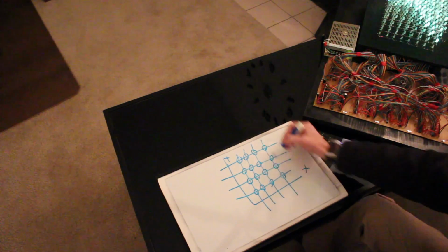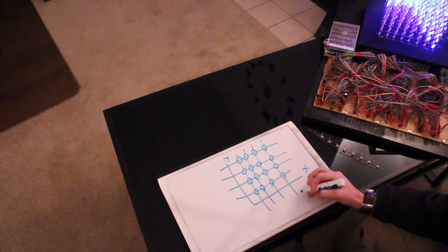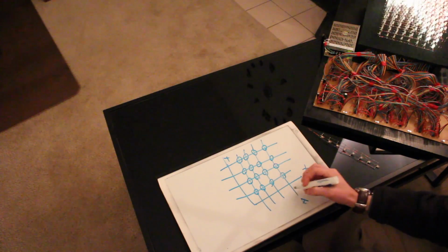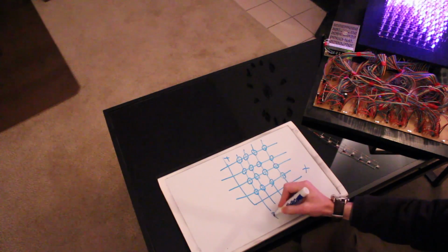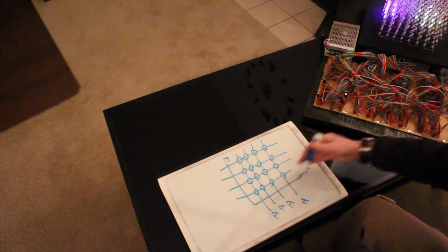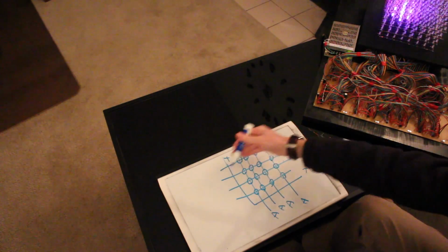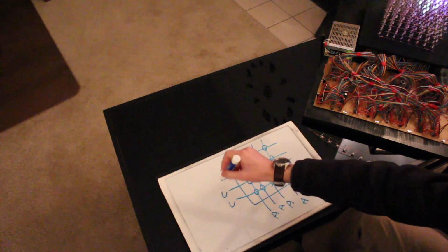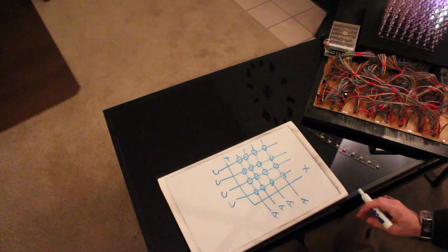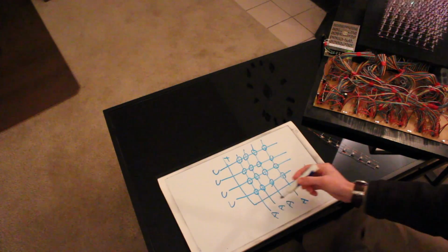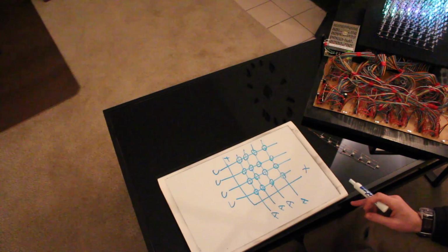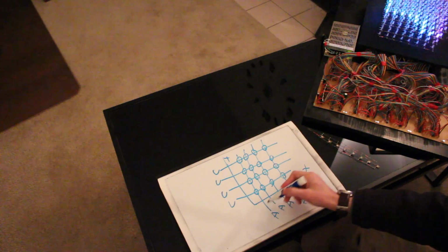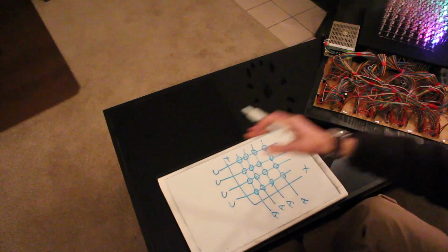And we want to control 16 LEDs, so we build up this grid, and we tie all of the, we'll call these the anodes, all the anodes together in all the vertical columns, and then we tie all the cathodes together in the horizontal rows. And then from this, now we can control any of the LEDs inside the grid via 4 plus 4, 8 pins.